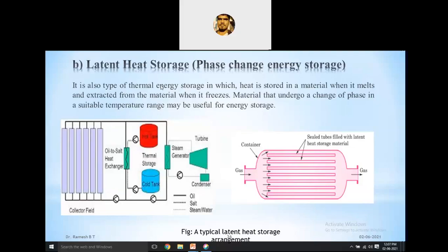Next, the phase change must occur with limited supercooling, meaning very low supercooling or superheating. Only if it is very low is the efficiency high. If there is more supercooling or superheating, the efficiency is reduced.